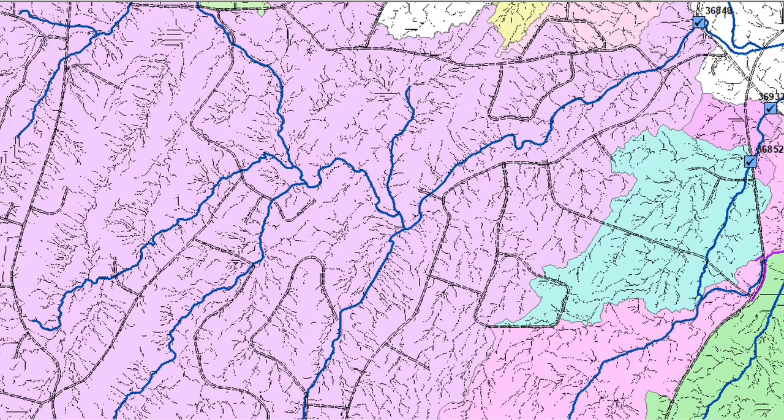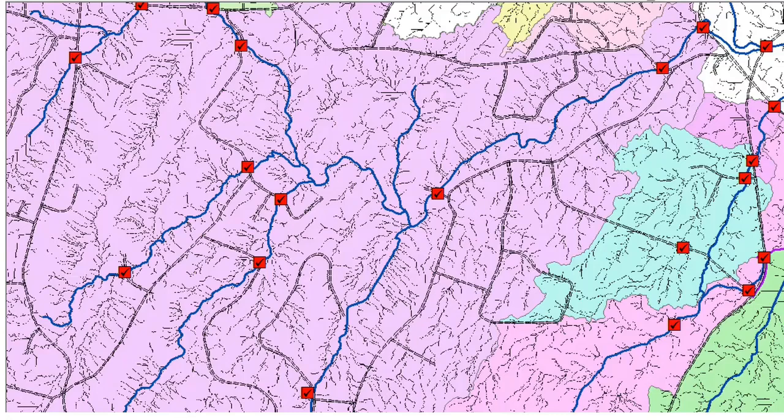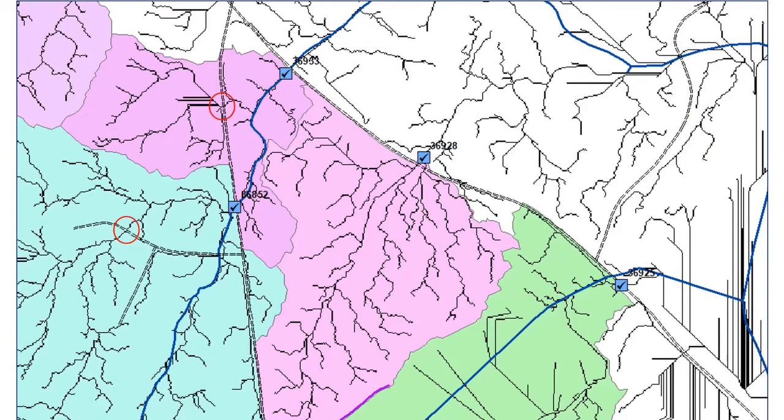And so this is probably a fairly accurate representation of the drainage area to these county culverts. But if we wanted to add town culverts into the mix, now we have a lot more culverts. So there's a lot more to check. And so the question is, how much do we edit at the scale of the analysis we want to do? So in this case, we need to go into these town level culverts and check. And then we only really need to edit where it matters.